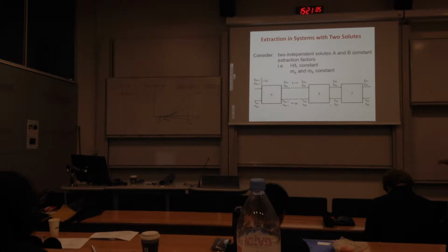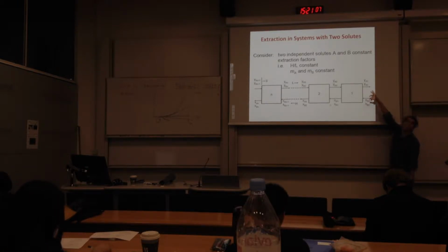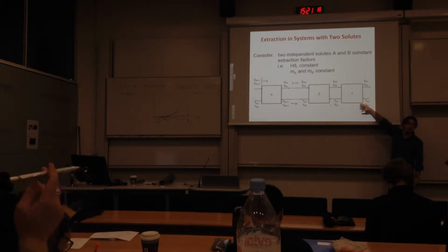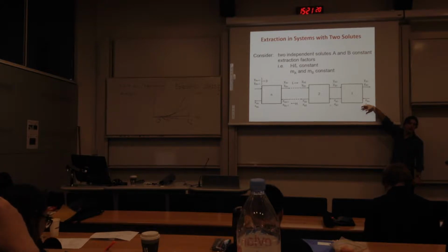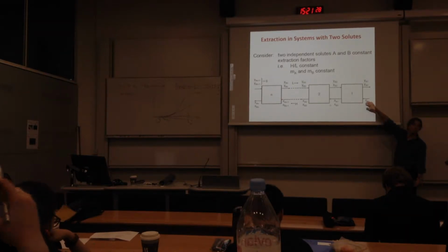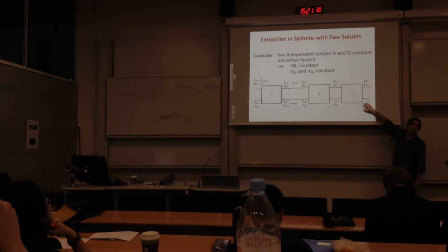So these compounds go to the kerosene phase. Normally, the extraction is based on keeping the fission products in the aqueous phase and extracting the uranium. But you can always design your system so you have conditions that make uranium more likely to stay in the aqueous phase.